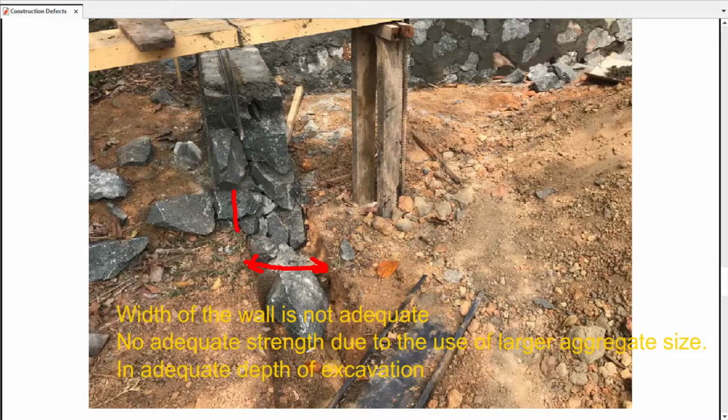You can see here they have put it outside the excavated trench. So at the top you have a higher width, but at the bottom you have a lesser width. This is kind of an error or a mistake that has been done intentionally. This is an intentional error, because if we know the width of the foundation is this much, they have to cut this trench to the same width. Therefore you have to be careful when doing the construction.